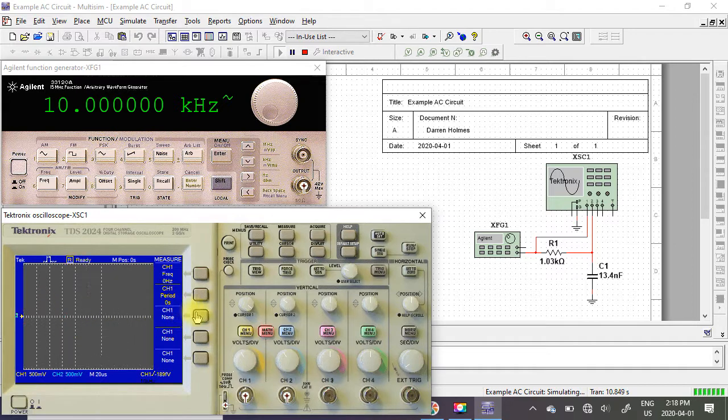On the next menu item, I'm going to click on its button, source channel 1, and in this case, I don't want type frequency or period. I don't want the mean voltage, I want the peak-to-peak voltage. And remember, we set up our function generator to output 2 volts peak-to-peak. So our oscilloscope's saying channel 1 is at 2 volts peak-to-peak. So I'm going to click on back.